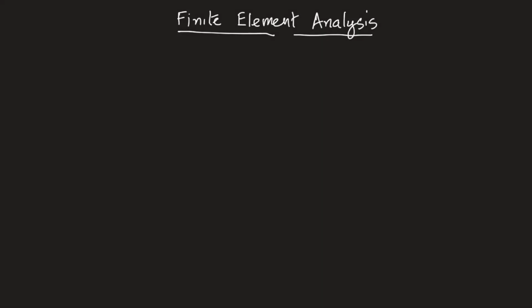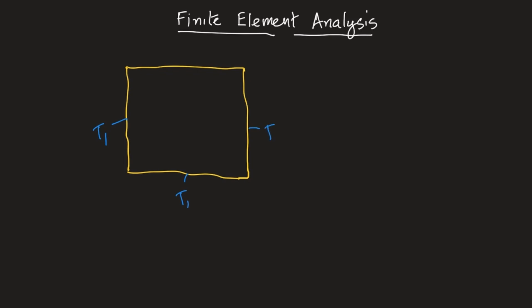Now let us see how problems are solved using finite element analysis. This video is intended to introduce some of the basic terms in finite element analysis. Let us consider the example of a plate where three sides are at temperature T1 and the fourth side is at temperature T2. The problem here is to find the temperature T at any location.